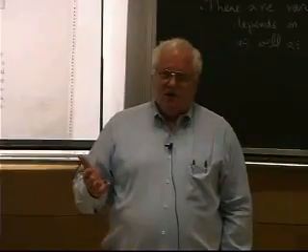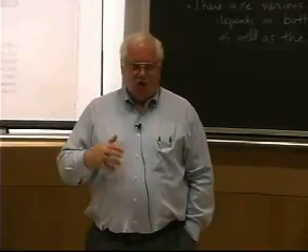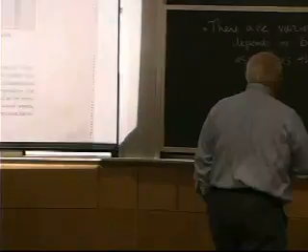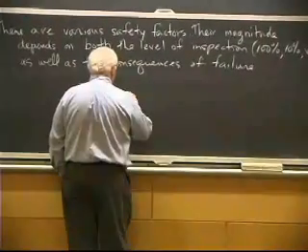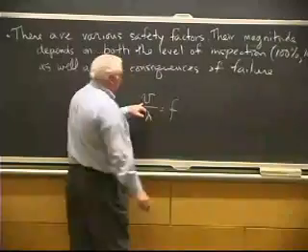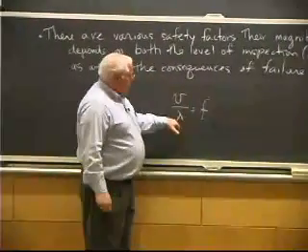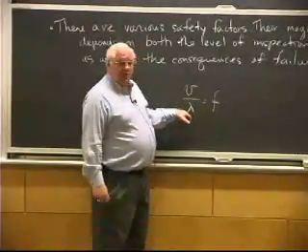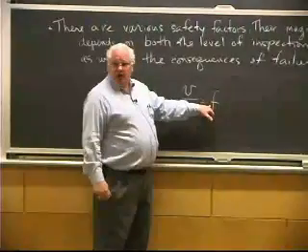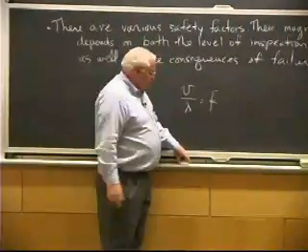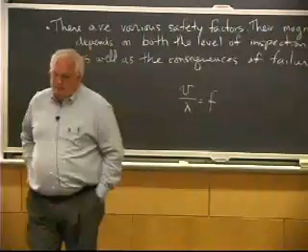At those speeds, to get wavelengths that are going to give me a flaw size, right? Remember, velocity divided by wavelength is equal to frequency, right? If I put 3,000 meters per second in here, and I put a wavelength in here of 3 millimeters or something like that, a size flaw I want to detect, you will get very large frequencies, okay? Do it for yourself, but you're going to be in the megahertz regime